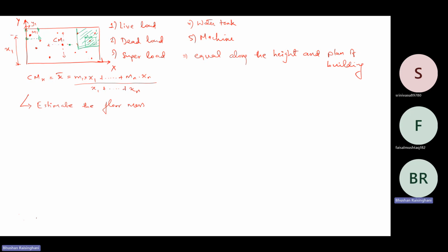So as per Eurocode, any slab of thickness more than 75 mm can be considered as a rigid diaphragm if it is continuous. If it is non-continuous, then also if it is not transferring the forces, then it does not become a rigid diaphragm. Like a floor with a very large opening, more than 50%, then you cannot take it as a rigid diaphragm.